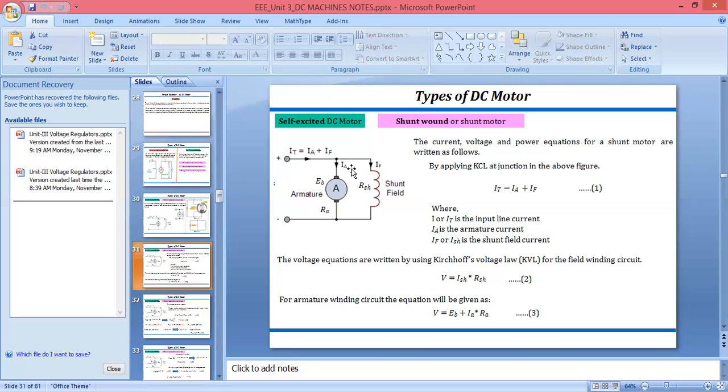It means we are supposed to derive the voltage that appears across each element, take the algebraic summation, and that will be equal to 0. Or we can take KVL as potential rise equal to potential drop, meaning the increase in potential and the decrease in potential.